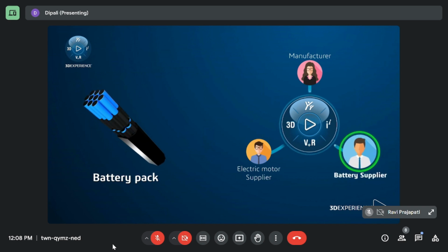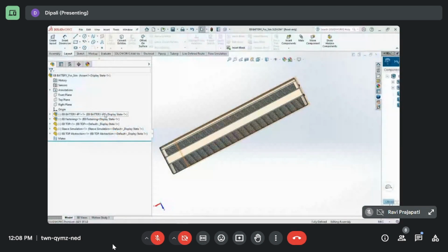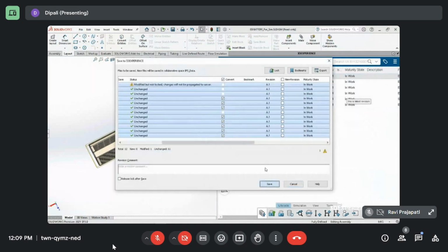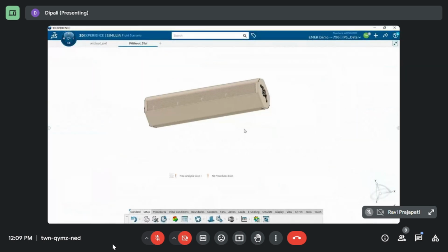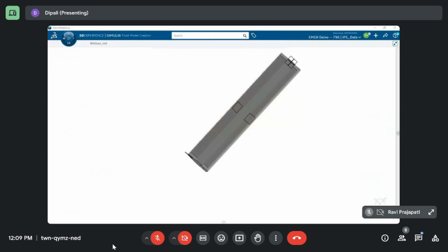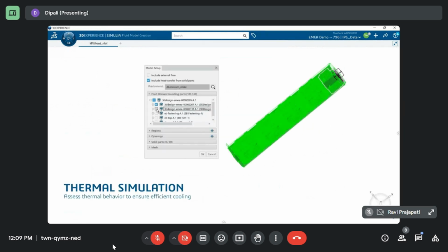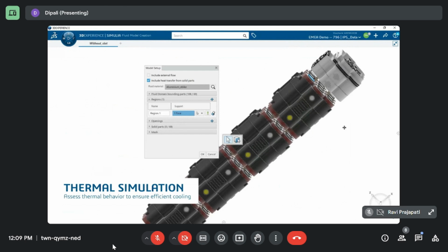They redesigned the pack in SolidWorks to include an additional battery module. Once the frame and motor were decided, the battery pack is composed of 10 cells, leading to a 4-module battery pack with a theoretical increase in range of 33%. A concern regarding the operating temperature of the battery was raised to ensure safety. By connecting SolidWorks to the 3DEXPERIENCE platform, they were able to leverage thermal simulation capabilities to assess the battery cell and casing temperatures at maximum torque operation.